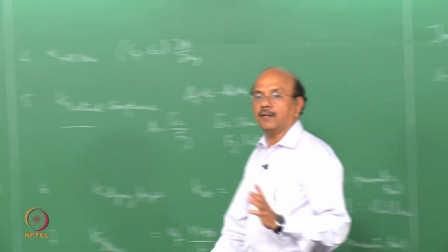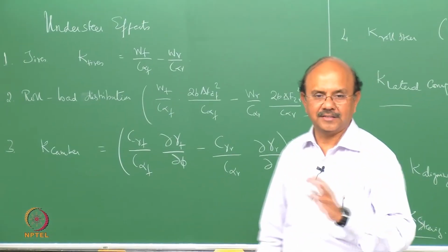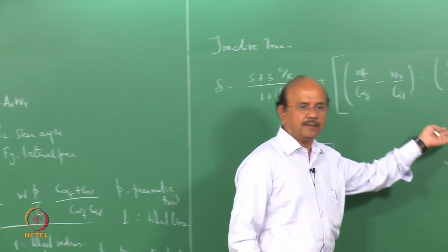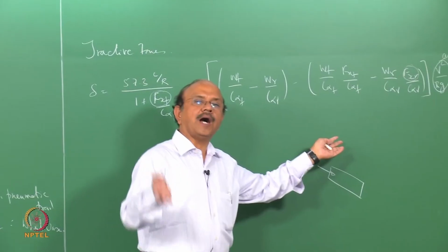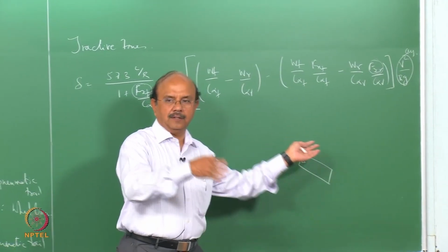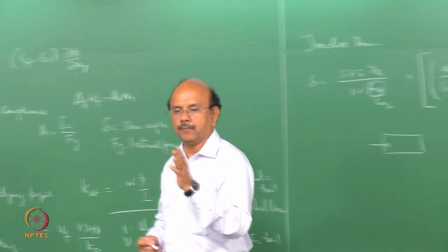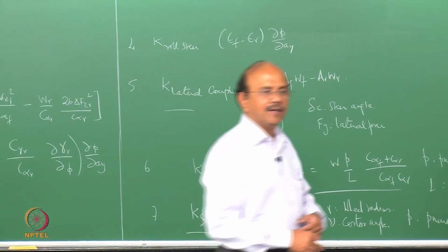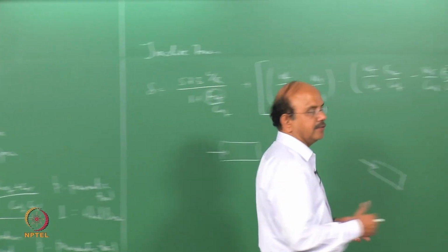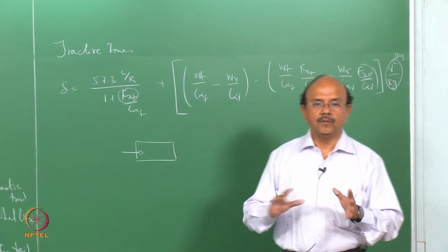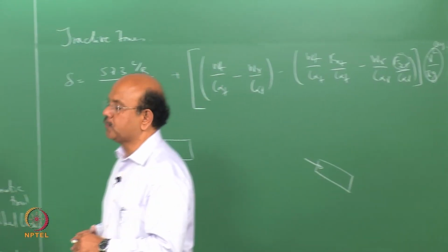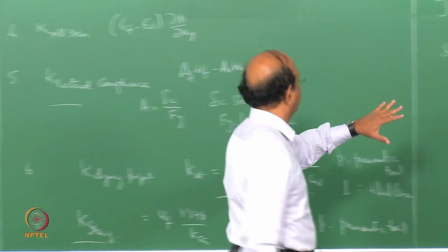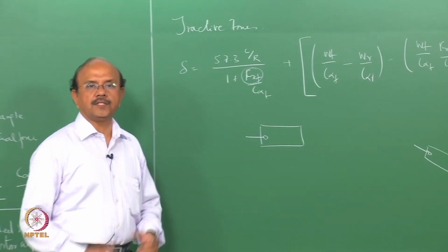So in other words, the front wheel drive has a tendency, because of traction, to be oversteered, but due to other factors like A and B, the distance between the front axle and the center of gravity location, that being small, has a tendency to understeer. Okay. So that is one of the contributions, or this term is a contribution for the understeer gradient.